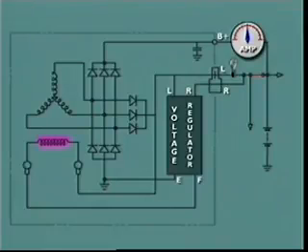The alternator is now set to be charging, and since the output voltage at the B positive alternator terminal is greater than that of the battery, the current flows to the battery to begin the recharging process.